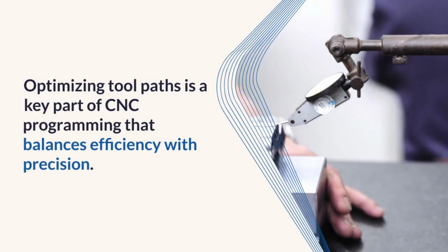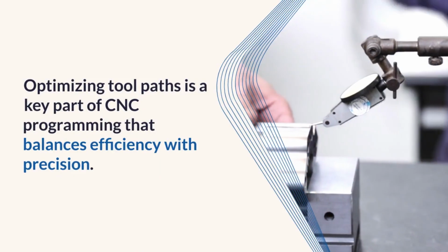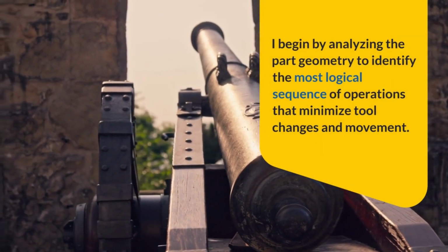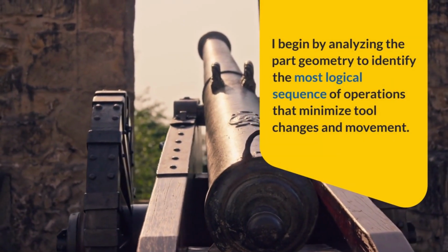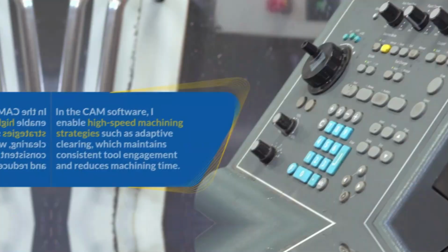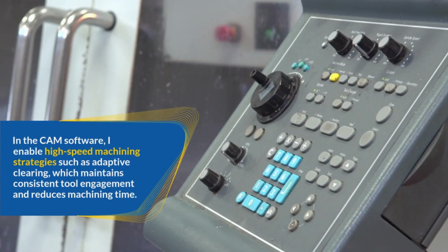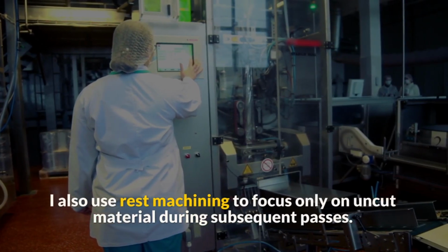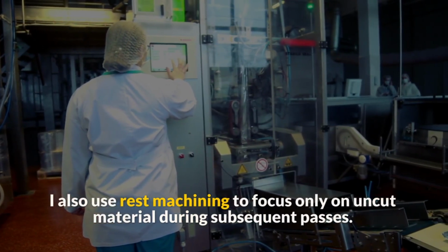6. How do you optimize tool paths for efficiency without compromising accuracy? Optimizing tool paths is a key part of CNC programming that balances efficiency with precision. I begin by analyzing the part geometry to identify the most logical sequence of operations that minimize tool changes and movement. In the CAM software, I enable high-speed machining strategies such as adaptive clearing, which maintains consistent tool engagement and reduces machining time. I also use rest machining to focus only on uncut material during subsequent passes.